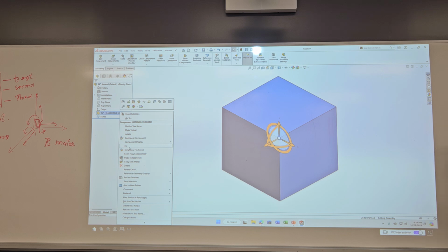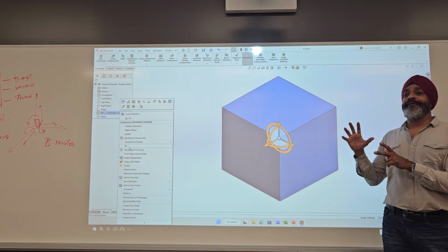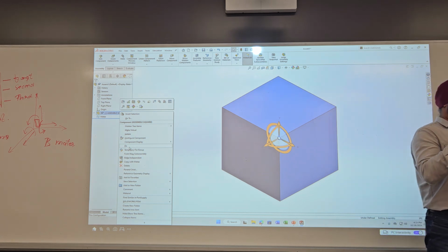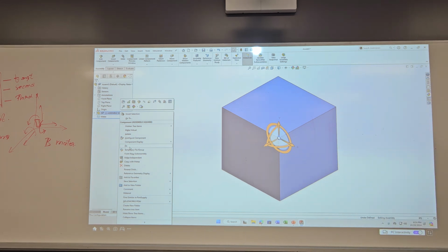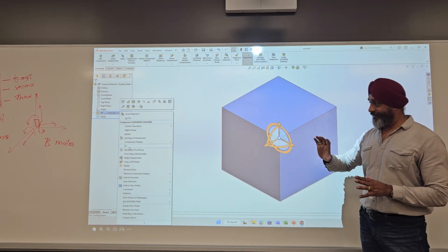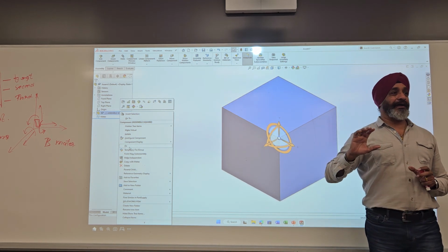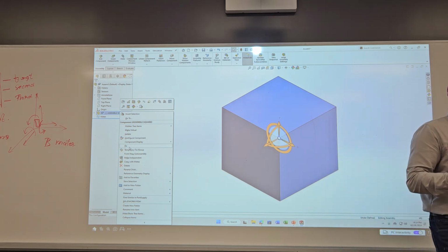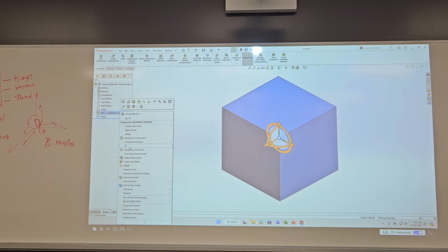That is your step 1. Then you want to make it align and fix really to the assembly environment origin around it. Again, we want to follow the origin, and you want to make sure your first part is fixed and fully defined by attaching it to the various faces or various planes, or the origin, depending on what your design intent is. Okay, and it all depends on your design.